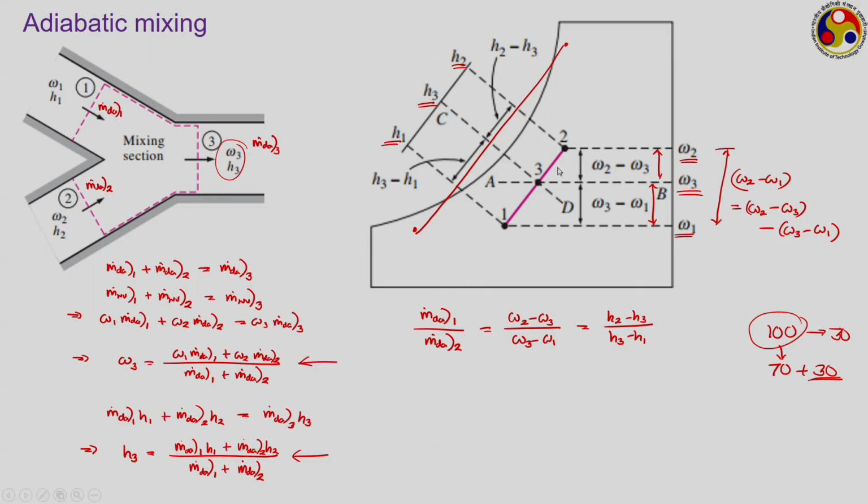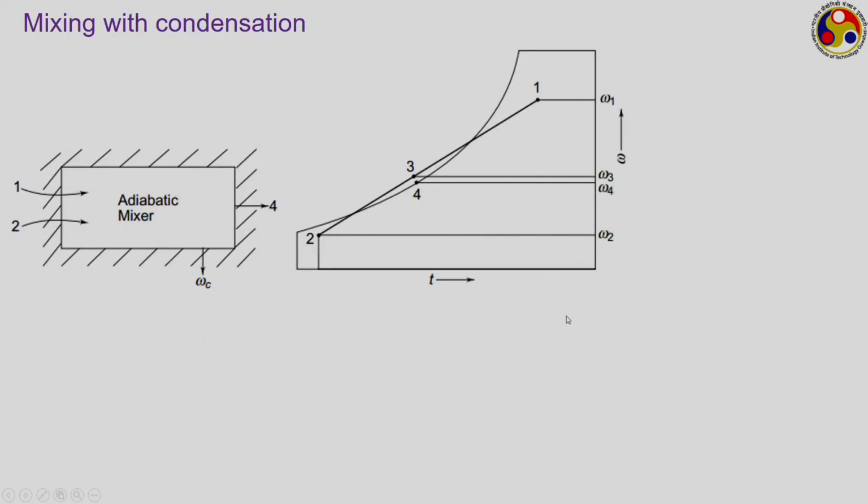In that situation, of course, the additional moisture that is present is unfeasible, and therefore, that additional moisture will get condensed, just like the situation here. In certain situations, we get this mixing with the condensation process. It happens when we are mixing one very cold stream of air and another quite warm stream of air, which is also high in moisture content.